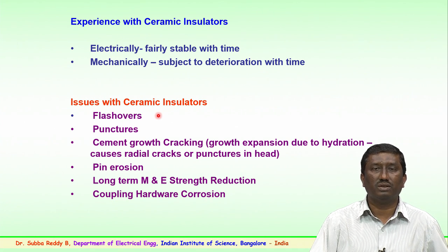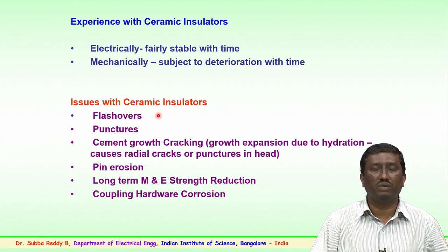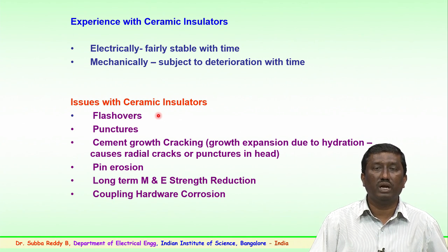In case of fog, mists or the early monsoon conditions, the surface becomes wet and starts conducting, and the flashovers do happen. We will be discussing the actual pollution flashovers in the coming slides, and why this phenomenon is important, because for very high voltages, extra high voltage and ultra high voltage, pollution or contamination which we have identified is an important design criterion to be taken care of.